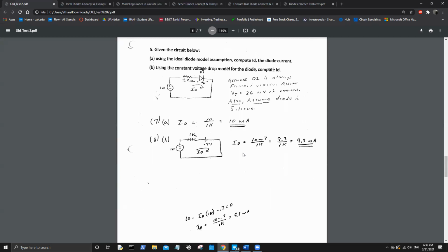Either way, the Thevenin equivalent was not too bad. So anyway, for this one with the ideal diode, we're just assuming it's a wire, right? Basically yes, because here's the thing. With part A, looking at the circuit, that is a linear voltage source, like a battery for our purposes. If you put a diode in series with a battery, it may as well be a wire. If we're assuming it's ideal, there's no voltage drop in the diode, there's no problem. It's a wire. And it's a DC voltage source. If this was AC, this would be a different story.